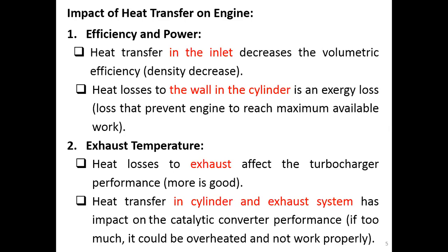So the mixture receives the heat. What happens to the mixture? The density of the mixture decreases, which means the volume gets bigger. So with the same amount of mass, it occupies more volume because the density decreases. So this is what happens if you have heat transfer in the intake manifold.